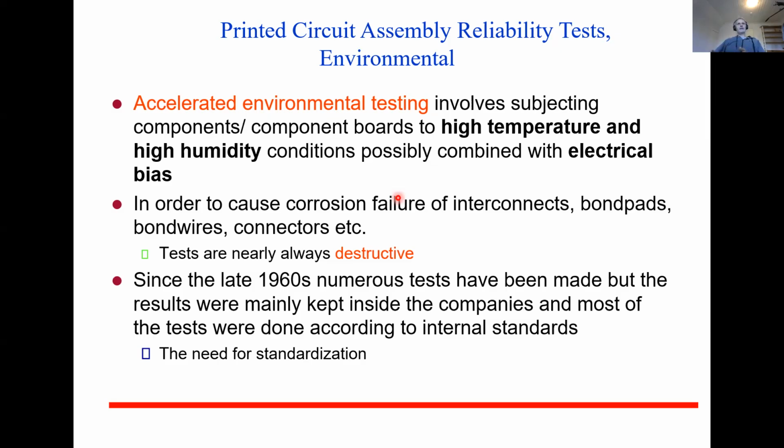And as humidity tests are destructive, it means that typically you don't use, there are exceptions, but typically you don't use temperature humidity tests as screening tests, because you don't want to force moisture inside your product.